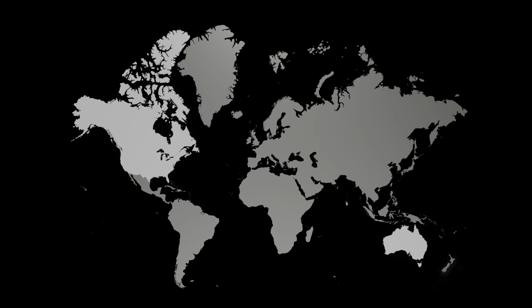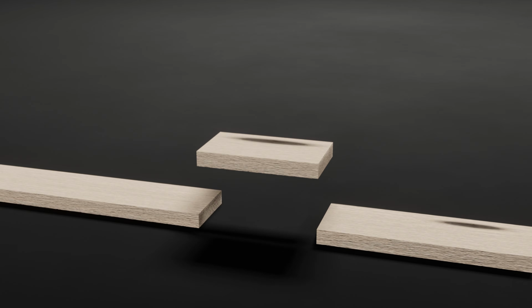The manufacturing process for cross-laminated timber starts with the careful selection of wood, often softwood. High-quality wood is chosen and any irregularities or defects are meticulously removed. Chosen wood gets scanned for moisture, and if any moisture is detected, the planks go to a drying rack before being used. This process ensures that only the best materials are used for later stages.